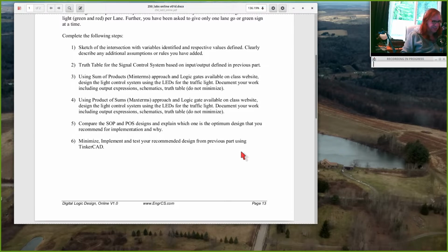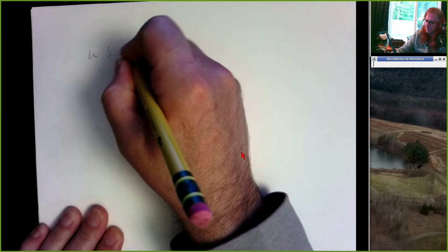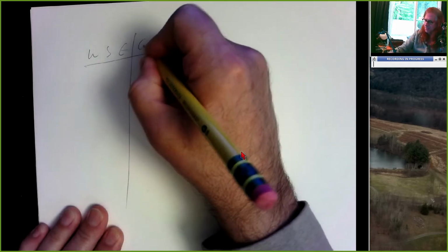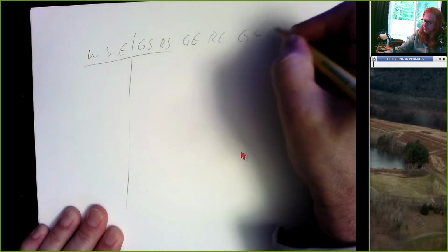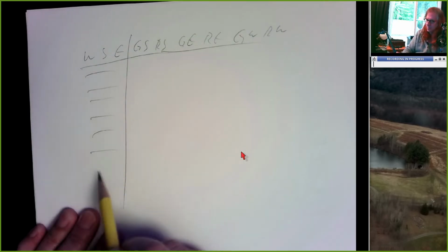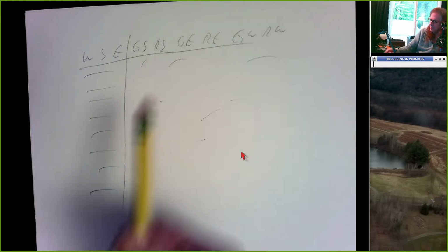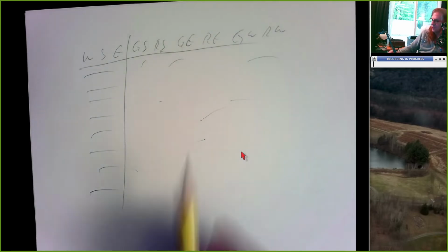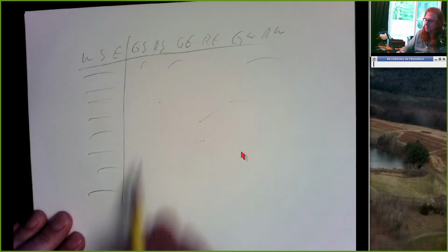Right, so that's, you know, here's our west, south, and east lights. And you can have green south, red south, green east, green west, red west. Whatever order, doesn't matter. 8 rows, 8 different rows, 6 columns, 48 output values, right? So this is basically 6 truth tables, but you can write it as a single truth table that lists each of the output values.